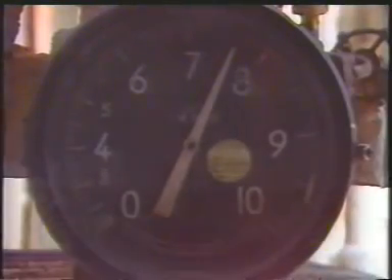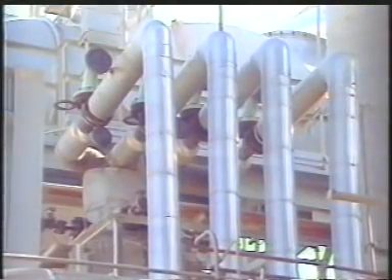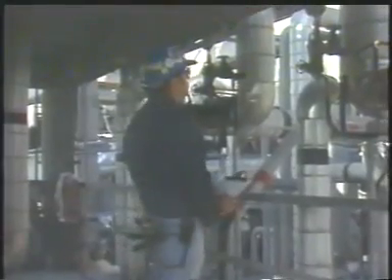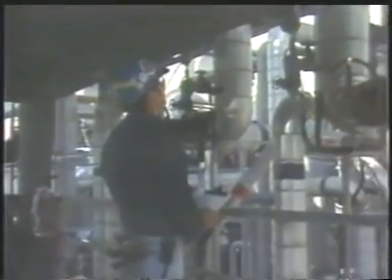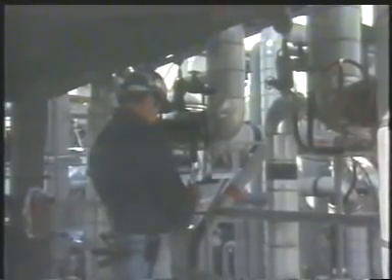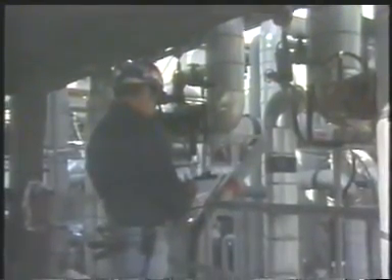Process flow rates are another key operating variable. The flow rates through each furnace pass, for example, must be kept balanced to assure even heating of the process fluid and to avoid tube damage due to overheating. The pass inlets and outlets are usually equipped with temperature, pressure, or flow instruments that allow an operator to monitor the situation and keep the passes balanced.